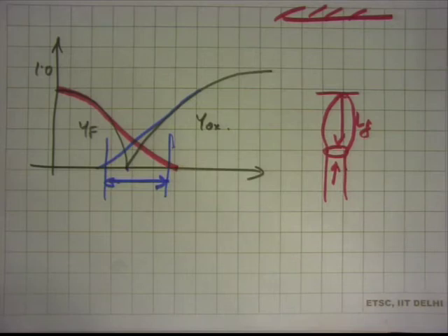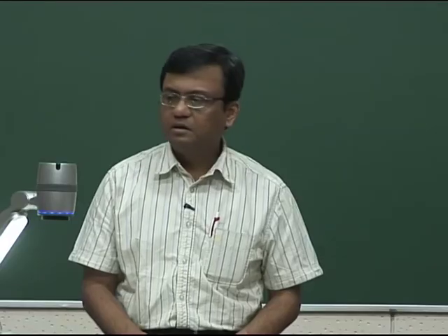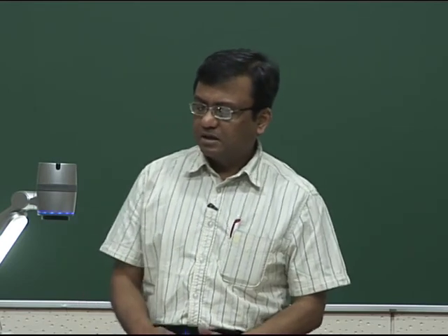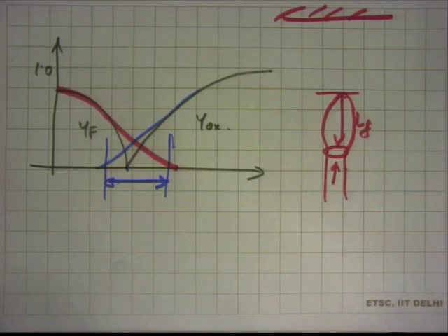Yes, because we have a mass flow rate, and we can calculate the surface area of the flame. Okay, so the response that I am hearing here is that we have an m dot of the fuel, then we have a flame area, so we have some density, so we can do m dot divided by rho divided by area to get some kind of a velocity. Okay, but there is a problem because the m dot that you are giving is actually the m dot of the fuel. It's not the m dot of a mixture. So that's one problem.